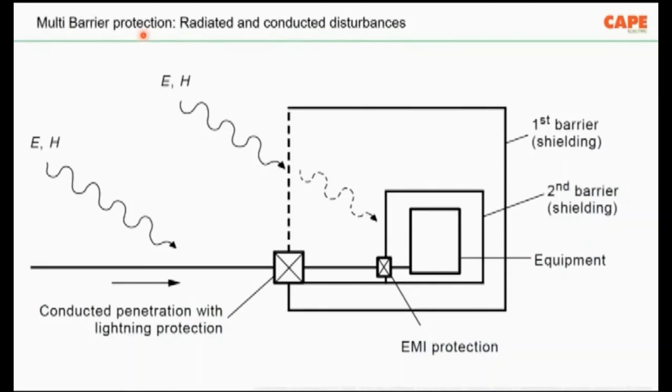Now, when we come to the electrical safety standard, such as our IS 732 or IEC 60364, the same concept which is followed for protecting electronics is also adopted in the electrical safety standard, and similar things are followed everywhere. Earthing, for example, means equipotential bonding.